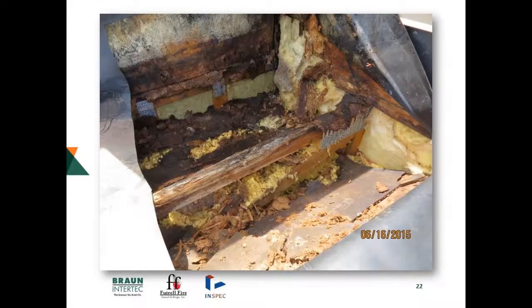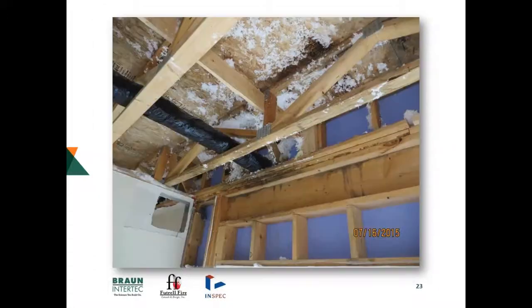Further opening that up, we see there's a lot of deterioration going on. The plywood, actually OSB deck in this case, dropped down into the truss space itself. And as you can see, there's a lot of moisture in there, a lot of mold, deteriorated OSB. The top chord of the truss is deteriorated. There is corrosion happening with the metal tie for the chord components. So a lot of damage going on there. That certainly is not what we want to have.